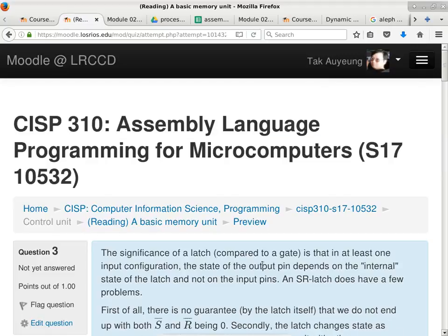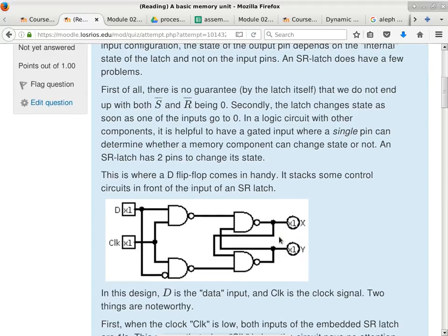Okay. All right. So now we have a circuitry that looks like two SR latches stacking on top of each other, right? Because when you look at this circuitry, we have one SR latch here with the little negation here, okay? Other than that, it looks exactly like an SR latch. And then we have a proper SR latch here, okay? So this is called a clocked signal. This is called a clocked flip-flop or D flip-flop that is clocked.